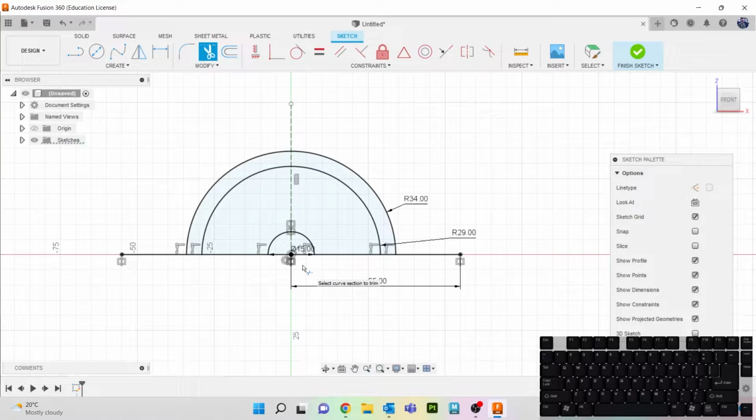So next thing I want to start doing is the teeth. So what we're going to do is they need to have an angle of 15 degrees. So what I'm going to do, that should be from here, and I'm going to just click like that. Then I'm going to hit D, do there to there, let me do an angle. And that should be, again, 15. I'm going to do divided by 2 because my math is terrible. Easy. And then I'll mirror that across.